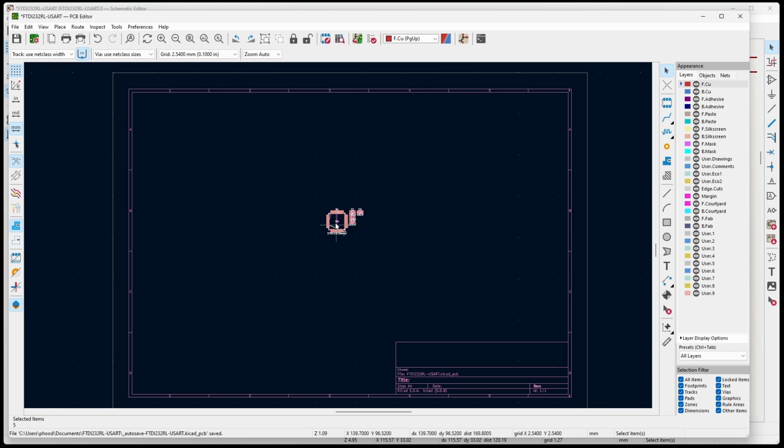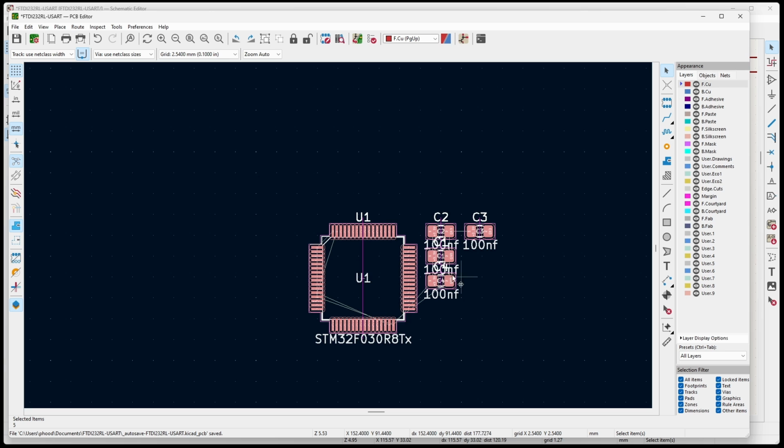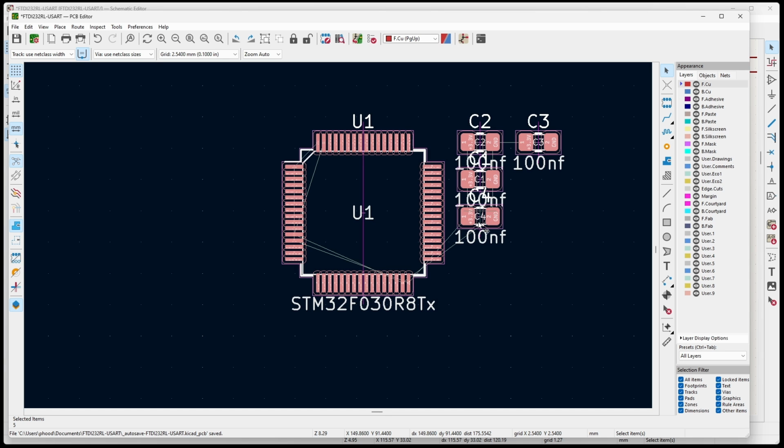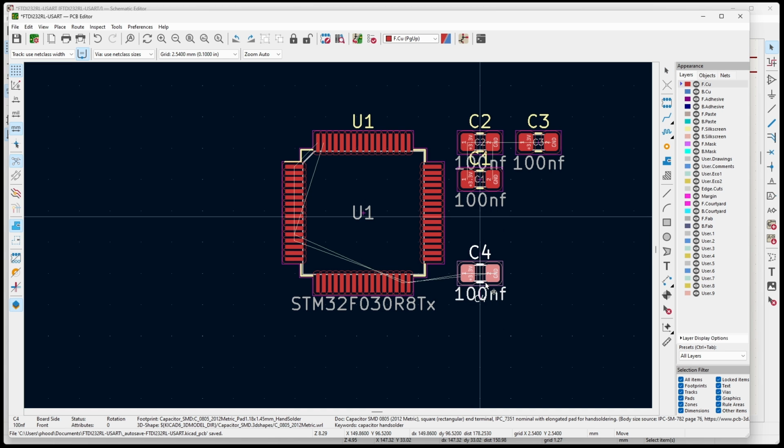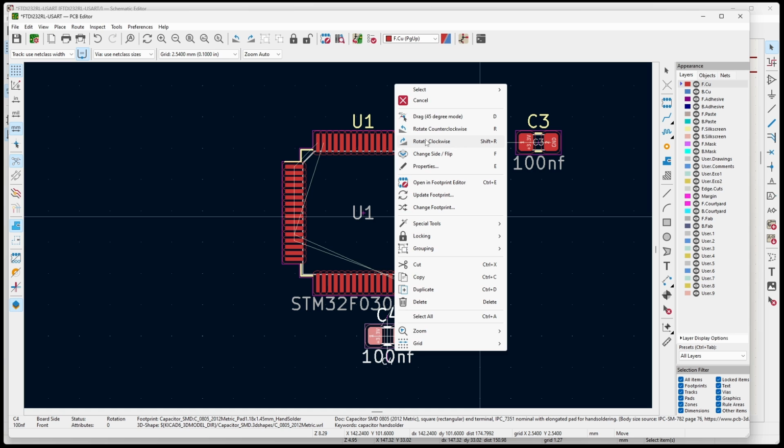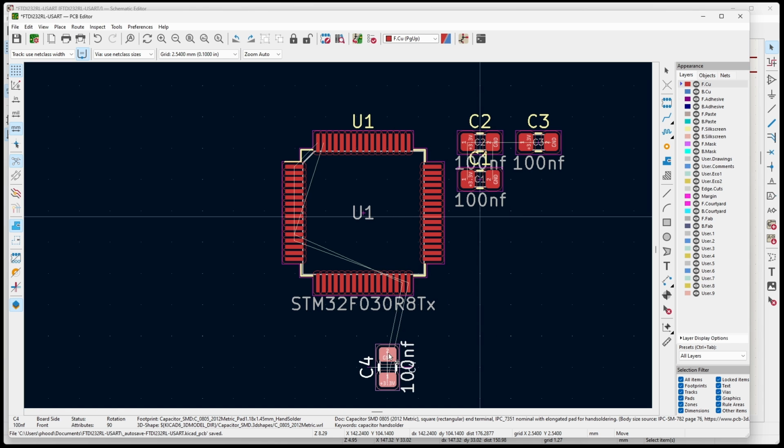anywhere on this sheet. So I'm going to zoom in, and you'll see how large those 0805s are. And I'm just going to place these footprints where I think they should be placed. I'm using the M command, or move, and I'm going to rotate it. You can use the R command to rotate. So I'll be doing that as I move them. And you can also change the grid spacing. This grid spacing is quite large, so I might want to do that. But I just want to get these into the general locations.